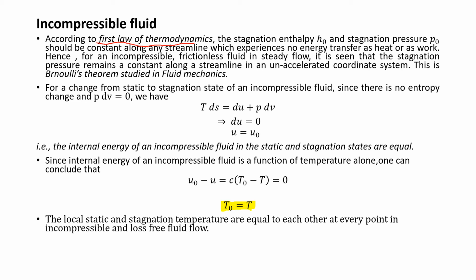Hence, for an incompressible frictionless fluid in steady flow, stagnation pressure remains constant along a streamline in an unaccelerated coordinate system. So this is Bernoulli's theorem, which we have studied in our fluid mechanics subject.